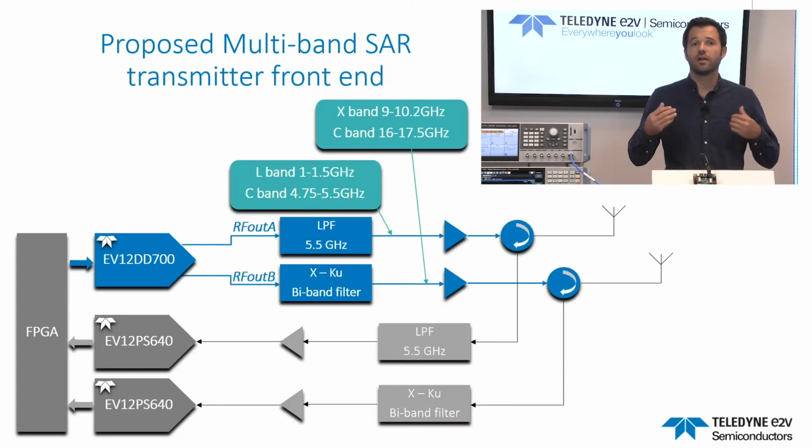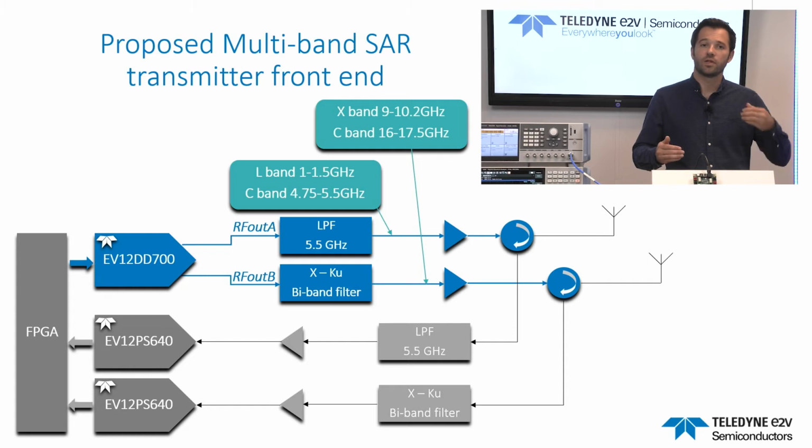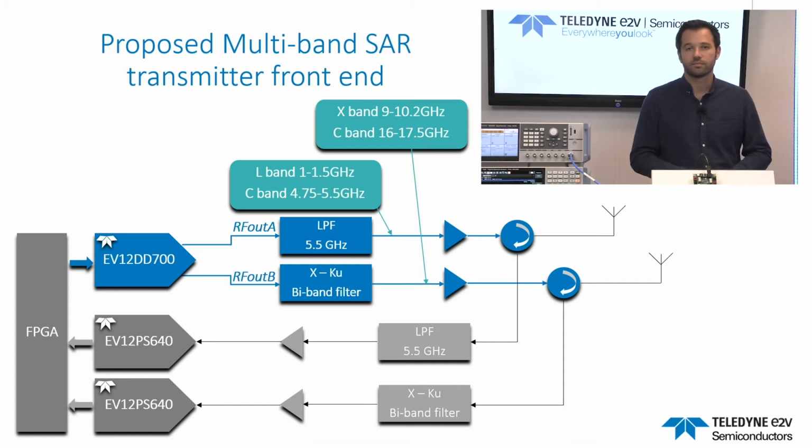Now, let's quickly detail the transmitter frontend. At DAC outputs, multiple stages are necessary. Filters to select the desired bands and to remove unwanted aliased bands before transmitting the signal to the antenna. Power amplifiers to meet the transmitted power requirements on each frequency band. And wideband circulators to share the same antenna between transmitters and receivers.